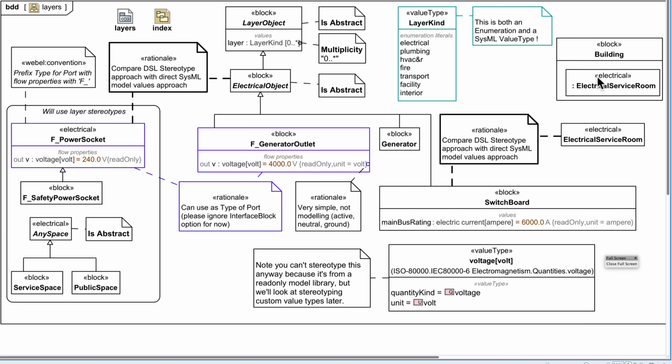It's showing through from the classifier because I don't have a property level stereotype applied. Now, if I were to create a property level stereotype and apply it to this, it's going to hide it. So think about what that means. It means the entire idea that we can use a block extension stereotype to indicate the layer membership of a part property has been undermined.